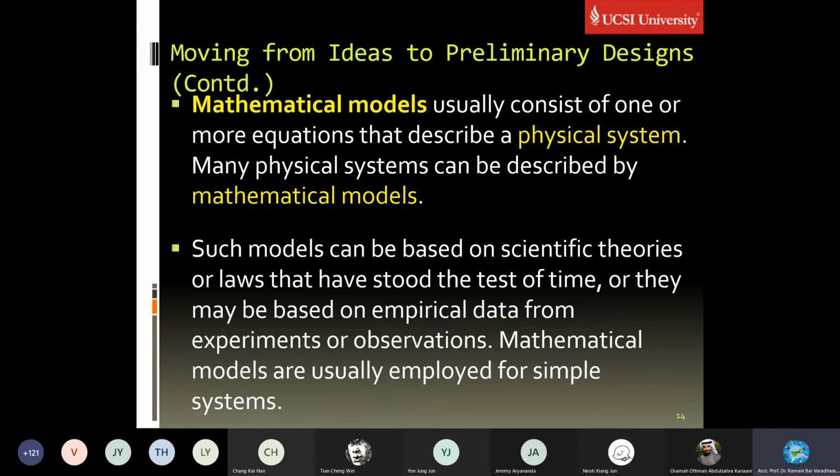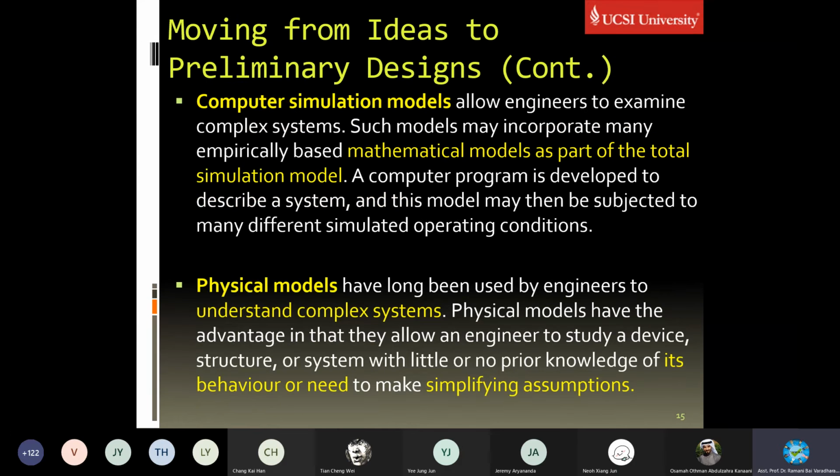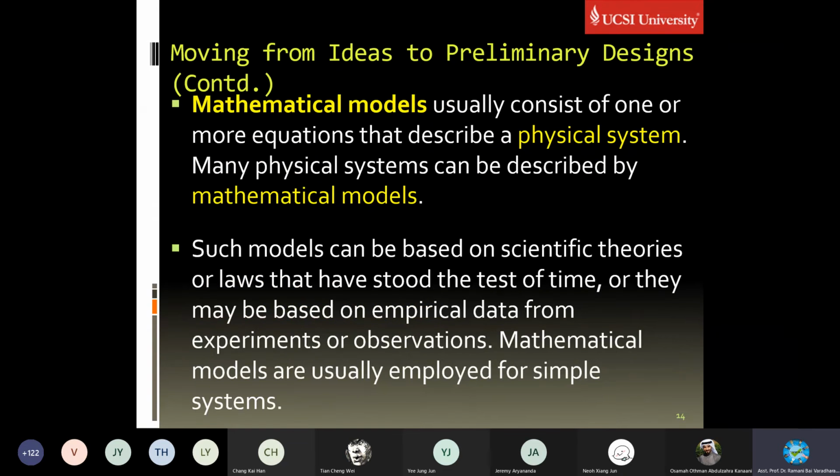Scientist A, engineer A, or economist A has done analysis for his own, taking his own catchments, his own people, his own region, communities, and analyzed and came out with the result. So they are all site specific. You cannot depend on their solutions or data. So be careful when you work based on these empirical data or relations or their equations. Or add your own coefficients, modifiers, or numbers that can be adapted in your region, so that you can still use this. Modify this equation, adjust the variables to accommodate your own problem, then you can use it.